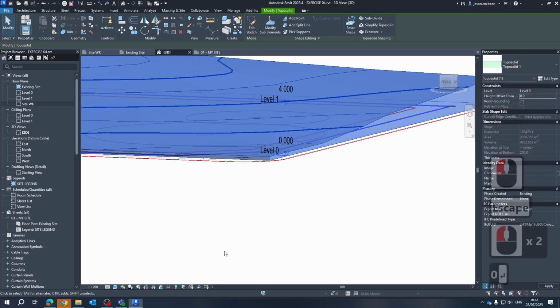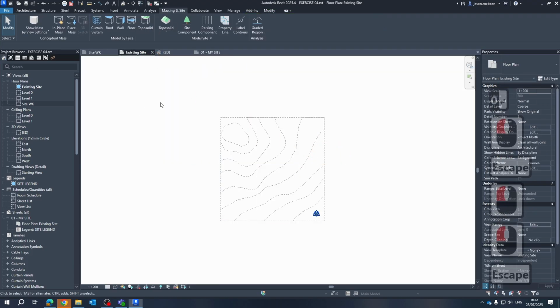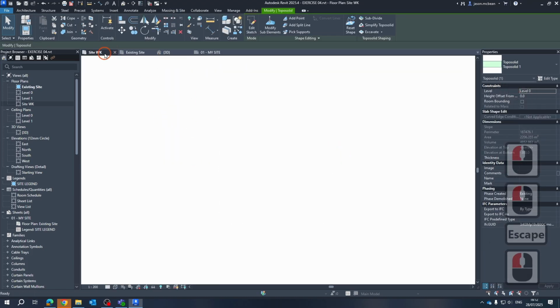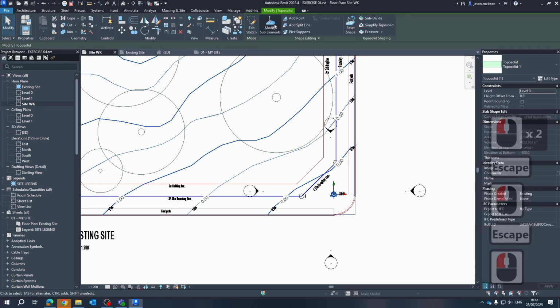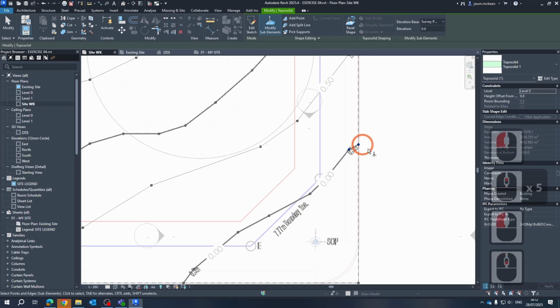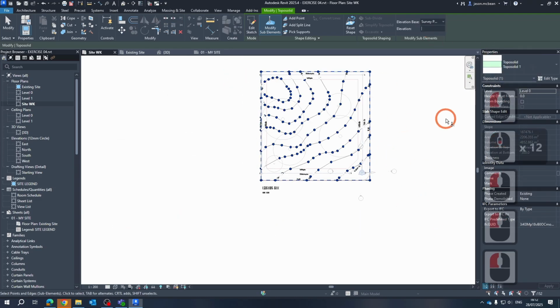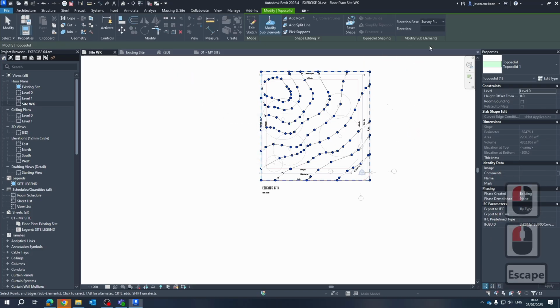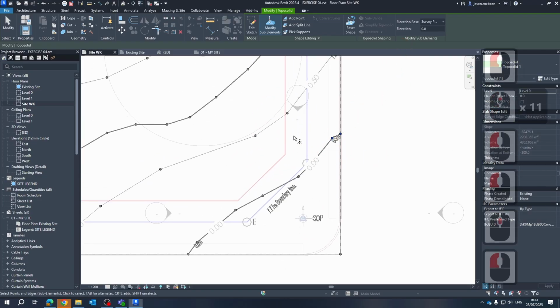So let's fix this 0. I have noticed this with this latest version of Revit. It is not that intuitive. The previous versions, I think this is maybe just a bug in this version. In the past, we didn't have this issue. Modify. Okay, so technically all of these have to be up by 500. We have to modify all of these shapes by 500. But now, typically, this will be 0. This will be 500.